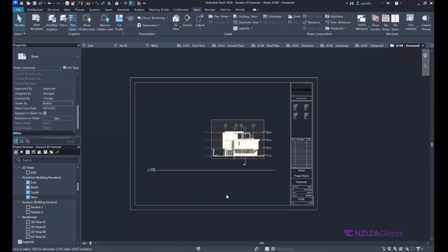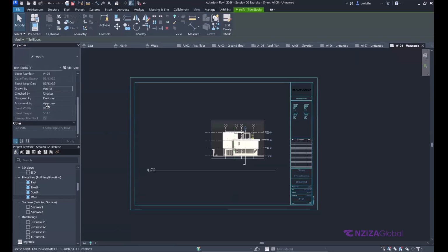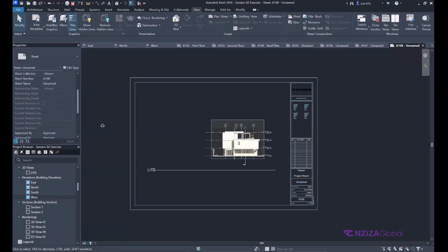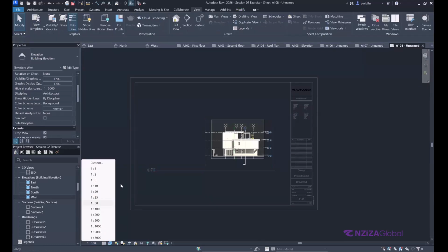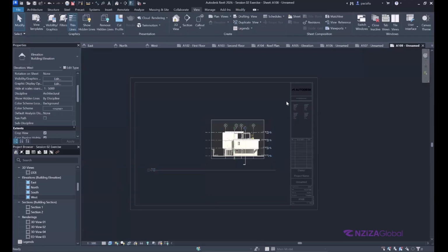If I have a landscape sheet and the detail of the drawings is cut off at the bottom, I want this to be clear on the right side. So I have to create it and edit. To edit the sheets, like this one, I'm going to take this, then change the scale to 150 so that it may fit.